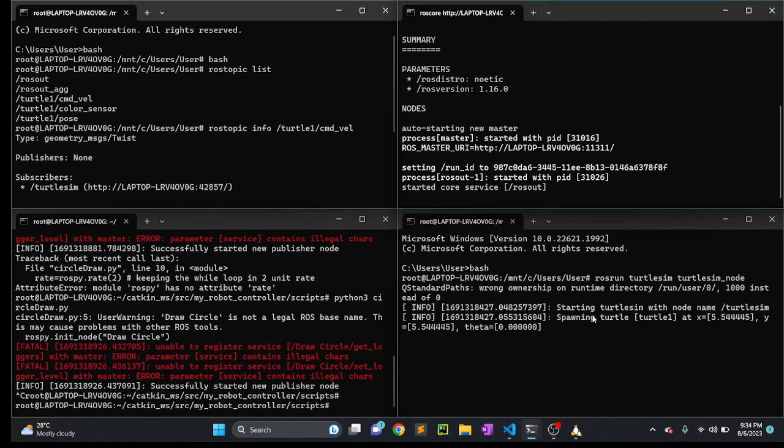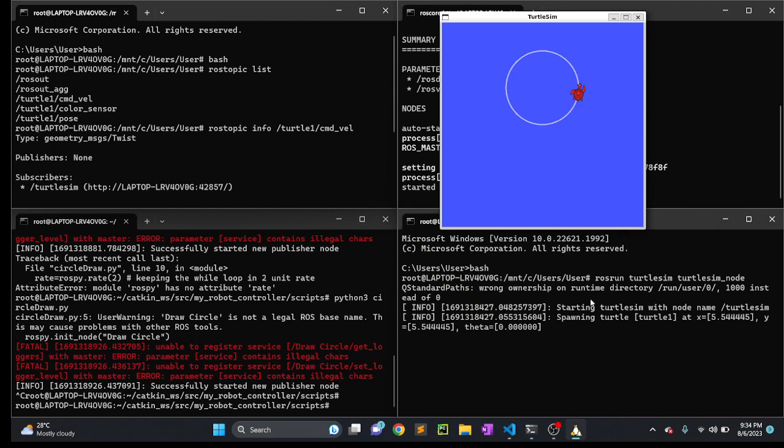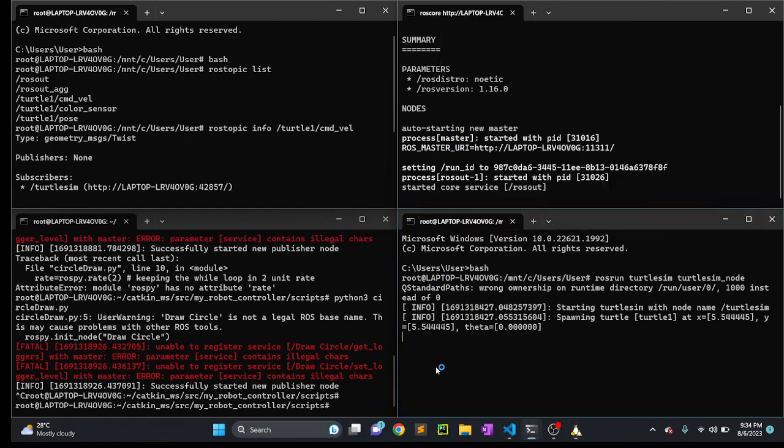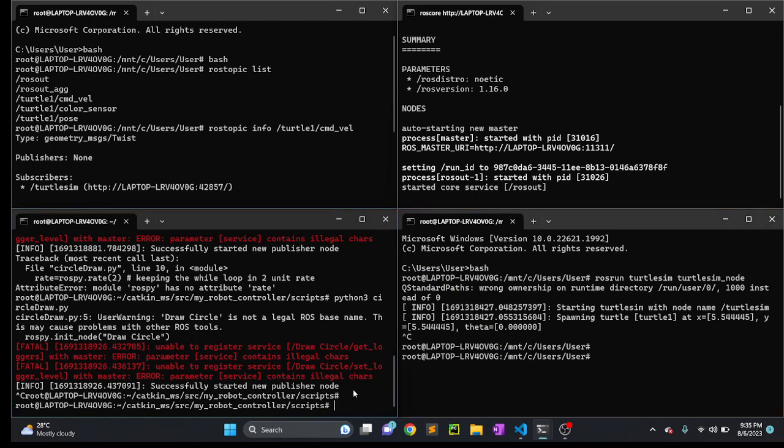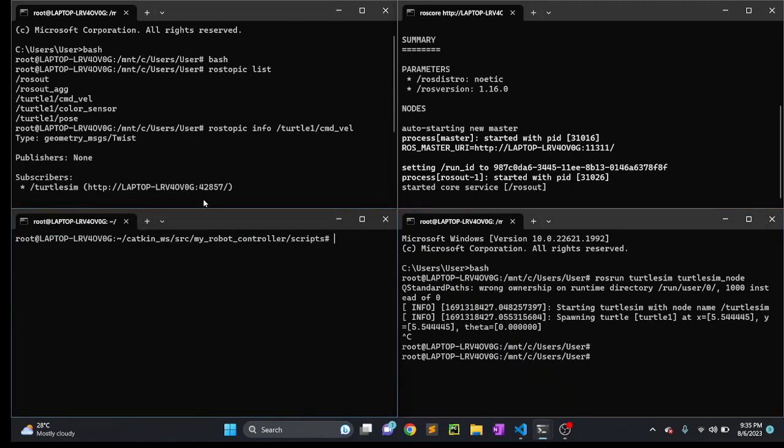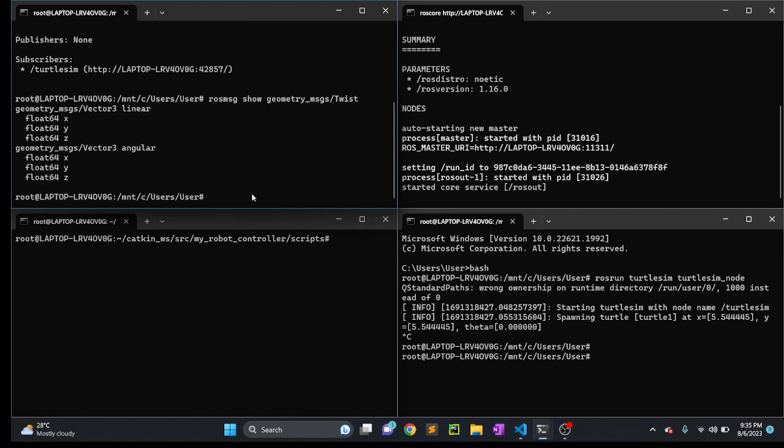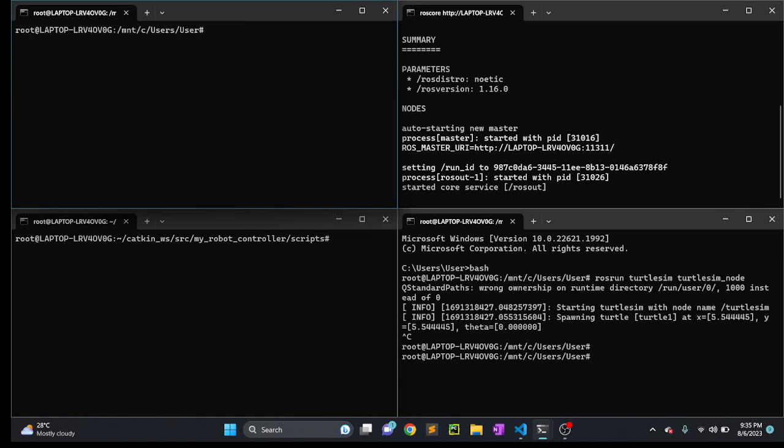this is our ROS code, so it will be continued like before, and in here I need to create a new simulation. So let me just stop this here, and I'm clearing this out. Okay, so yeah, I'm using the previous procedure. So the pose subscriber dot py is now our destinated subscriber node that we are going to write.